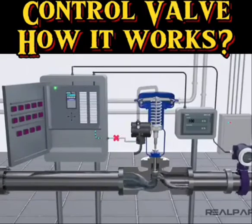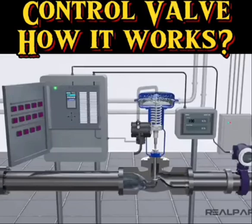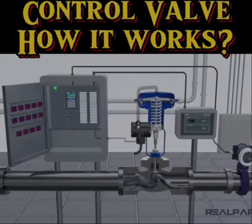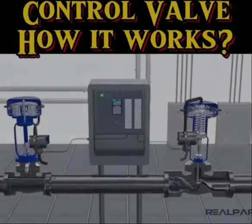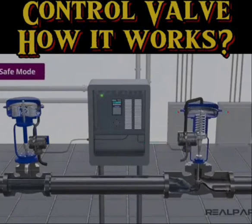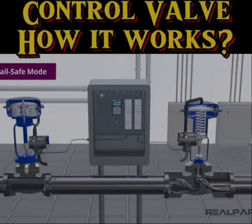the control signal occurs. As the supply air pressure is increased, the rubber diaphragm pushes against the spring and moves the valve stem down into the valve body. As the supply air pressure is reduced, the spring will move the valve stem out of the body. The position to which the control valve is moved, if a loss of signal occurs, is referred to as the failsafe mode.